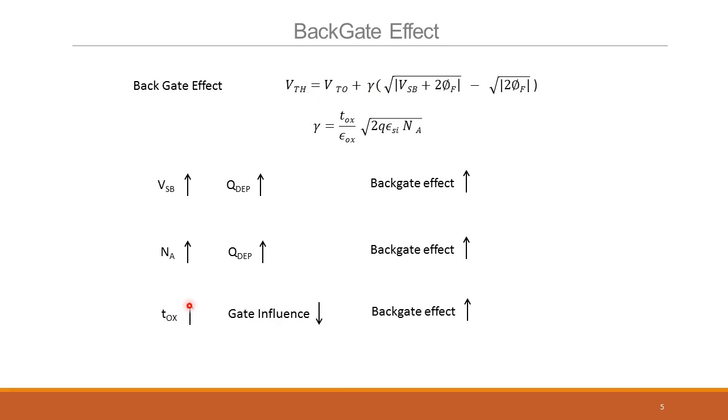So in deep submicron technologies where the gate is much thinner, Tox is much thinner, the backgate effect is not so high. Okay. So you can still play with the VT. So you do reduce it, that's how you could reduce it to 200 millivolts. Right?